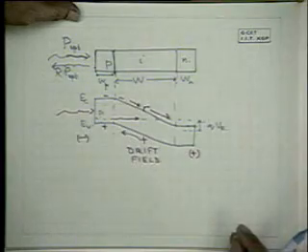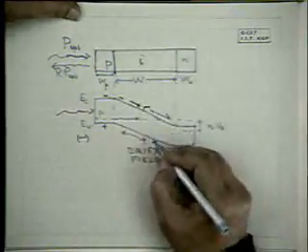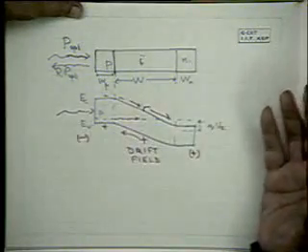Pardon? No, it is not an insulator. It is relatively lightly doped. I stands for intrinsic, right? But it need not be absolutely intrinsic. It is relatively lightly doped. The Fermi level should be somewhere near the middle of the band gap.